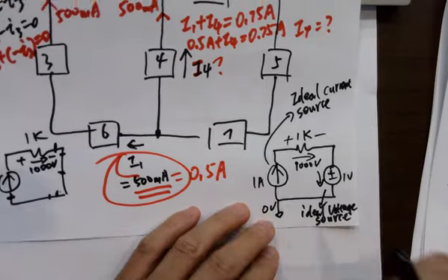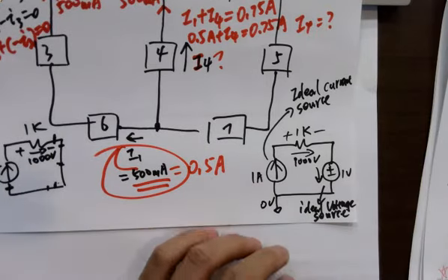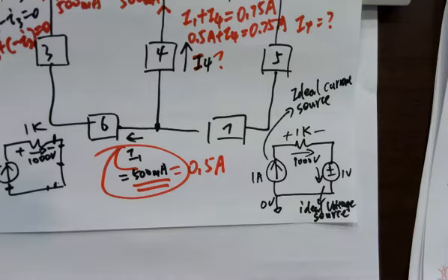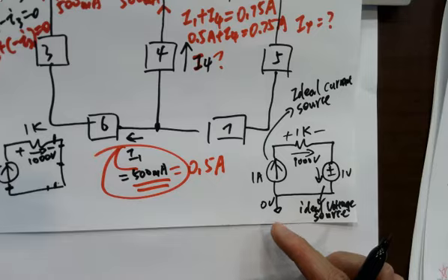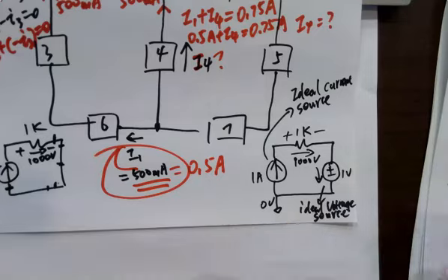See, here's 0 volts, right? Ground. Even though a lot of circuits in the problems don't have a ground pin, you can always just assume a ground, usually at the left bottom corner of the circuit, or the cathode of the battery. Not always the case, but for this case, you can do it that way. It's easier to analyze, okay?